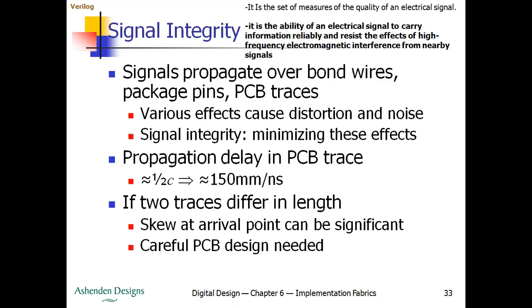So this won't affect much for a simple circuit. But if you have a larger design, a huge PCB, then we need to take care of the total path delay in high speed designing. In high speed designing this propagation delay does matter, and in simple circuits we don't need to worry much about this.